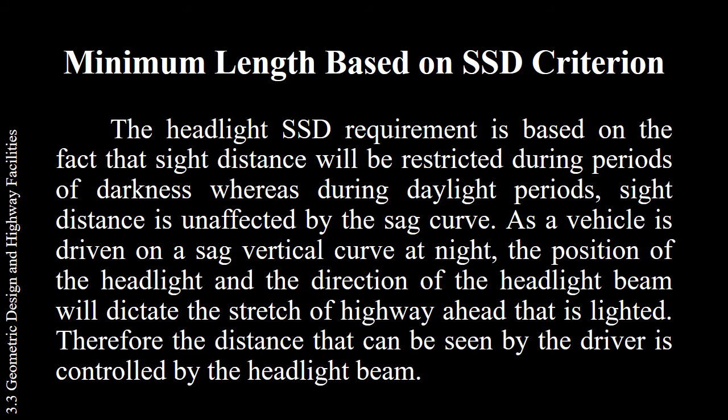Minimum length based on SSD criterion. The headlight SSD requirement is based on the fact that sight distance will be restricted during periods of darkness, whereas during daylight periods, sight distance is unaffected by the sag curve. So in short, it is just considering that the light should see the other vehicle passing forward or towards that vehicle.